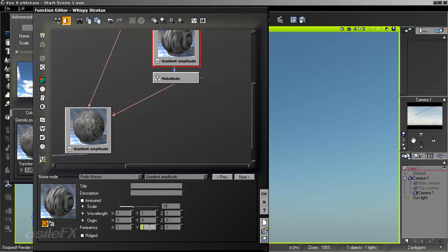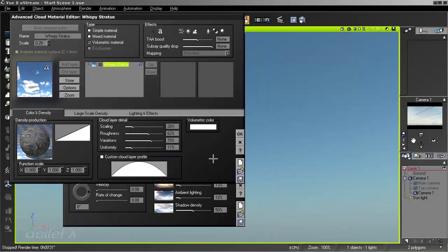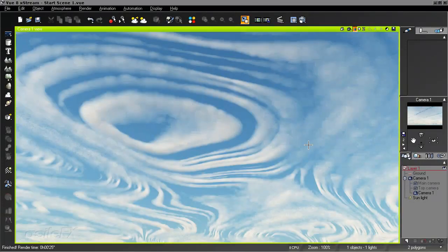I'm going to decrease the amount. You could also reverse it too. If you wanted to have this lower node have the increased frequency, and go back to the noise and set that to 1, that could sometimes work a little better. I'm going to go ahead and change the Y to 2 on both. And let's take a look at how this cloud layer looks. And so you can start to see the stretching and the turbulence around the initial node. And what we really need to do is kind of break off specific areas of the node, mix it in a little bit more so that it's not this constant amount of cloud, and we can get something a little wispier.